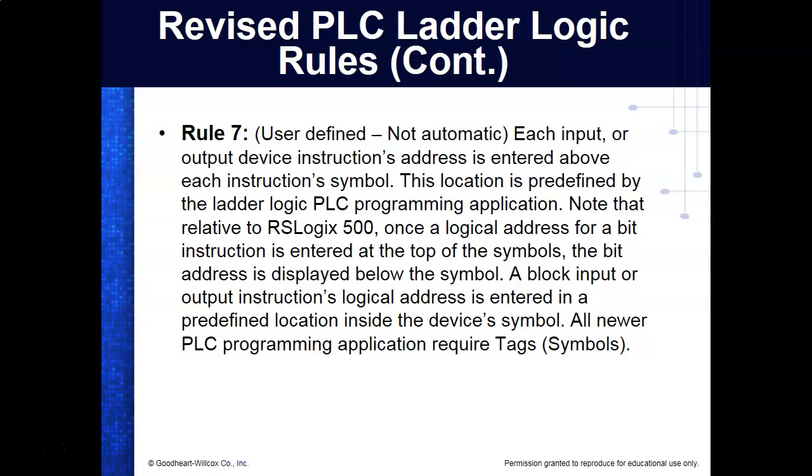Once the logical address for a bit instruction is entered at the top of the symbol, the bit address is displayed below the symbol once you hit enter. I need to add this. A block input instruction, which we'll look at later on when we get into counters and timers. A block input or output instruction's logical address is entered in a predefined location inside the device's symbol. So we'll look at that.